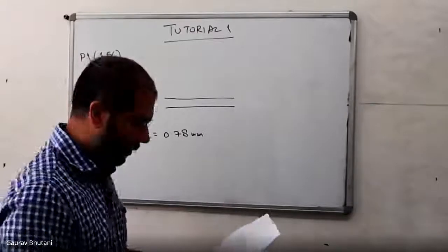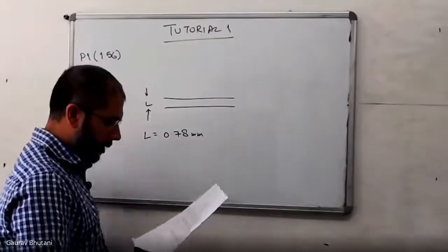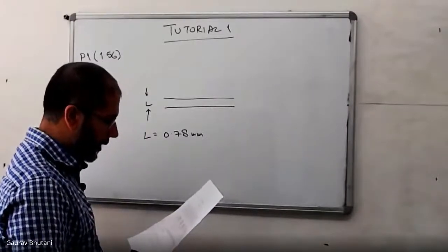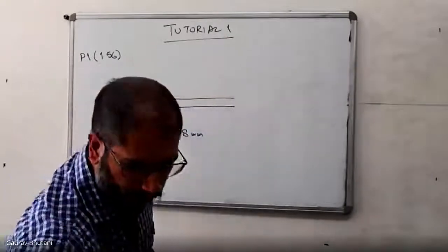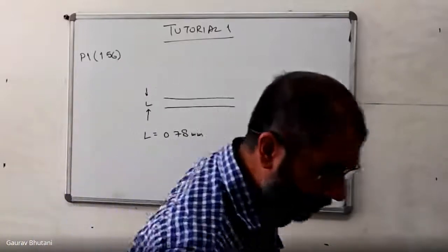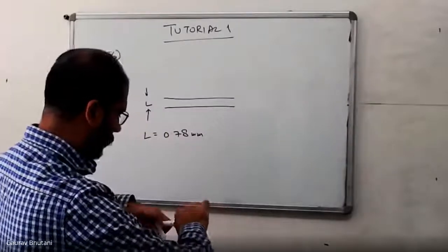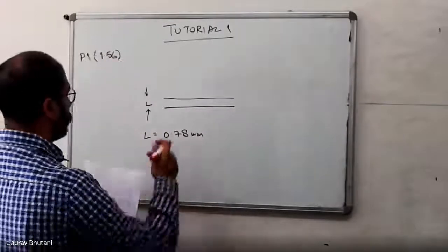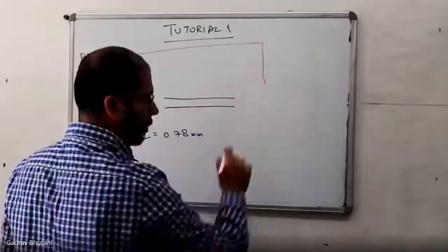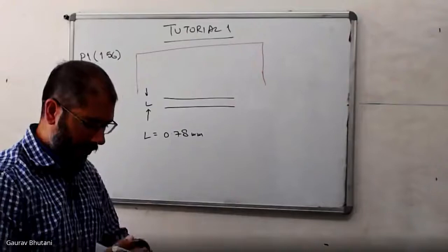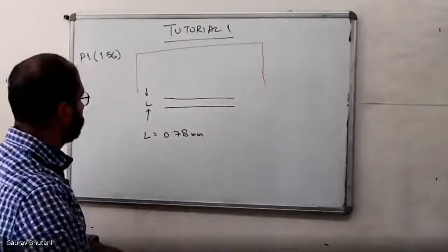So this is less than a millimeter thick. That's how thick silicon wafers are. The process for annealing this includes an evacuated chamber. So you have this in a chamber. It's evacuated, which means you're trying to remove as much air as you can, so that there is no conduction or convection because of that. So the only mode of heat transfer you have here is radiation.